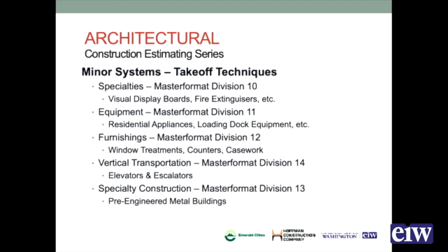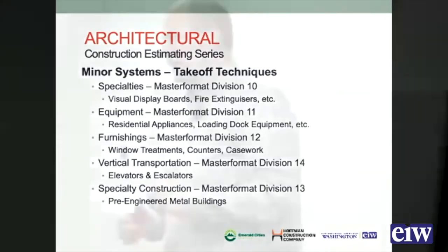And I've flip-flopped these there because you often see elevators and escalators, and technically that's part of the architectural piece of it. If you're looking at it as a general contractor, we look at them as type of elevator by stop. So how many stops does it have on the floor? You're always going to want to go get a quote for those, because elevators and escalators are only done by certain subcontractors. So that's where you need to go to make sure you get your pricing right.